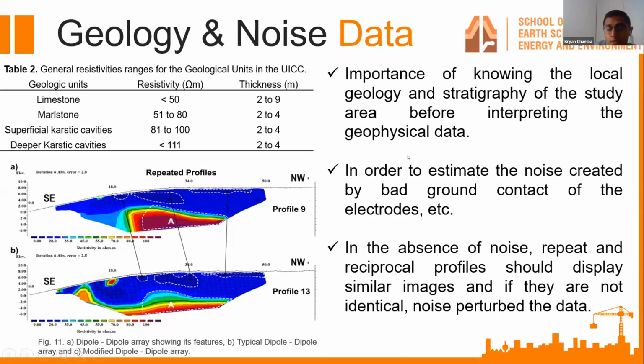And what is important to say this? It is important because according to the literature, resistivities could vary a lot according to the geological unit, but in our research, we have defined really a specific range of resistivity for each geological unit.